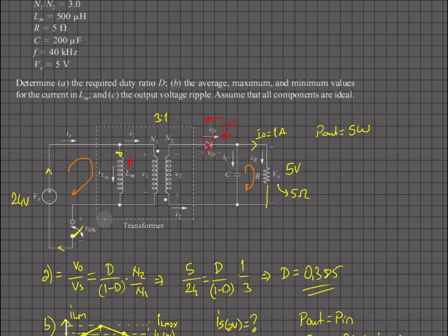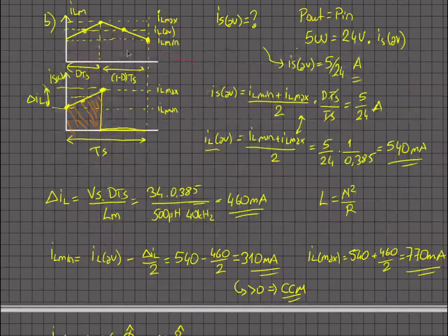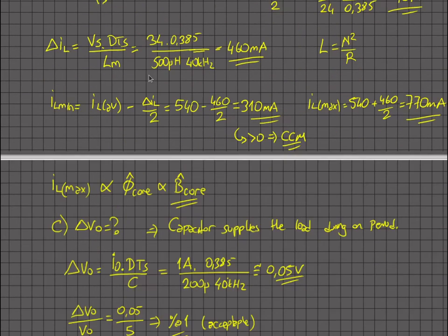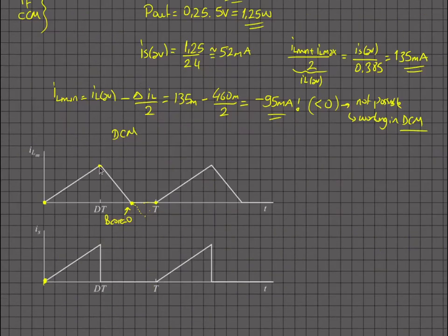Whenever we turn off that switch, the inductance current is charging the capacitor, but now that amount is shorter, because our current in the LM comes down to 0 quicker than (1 minus D) Ts.